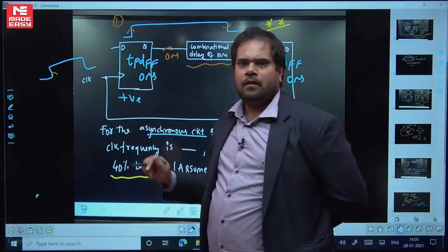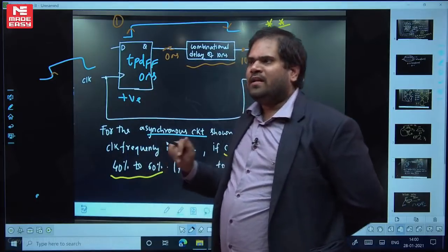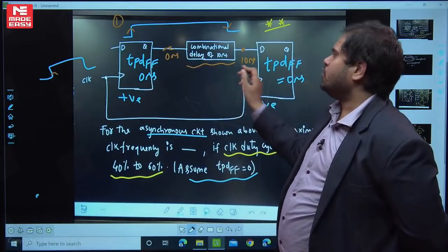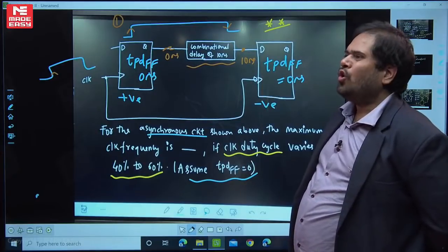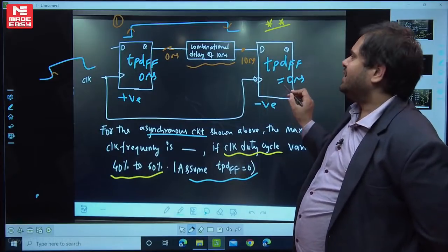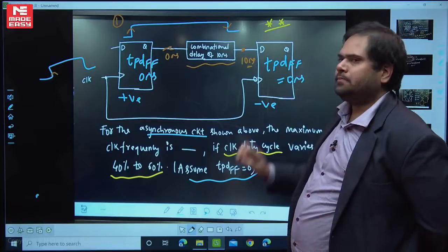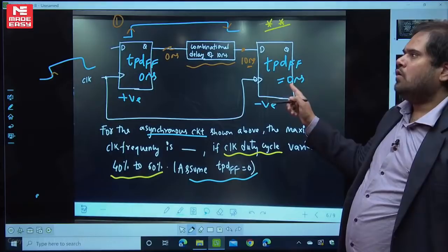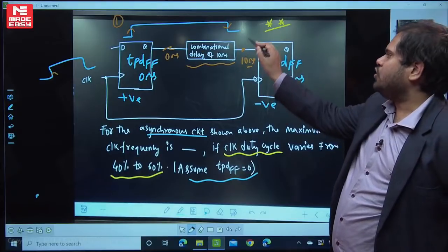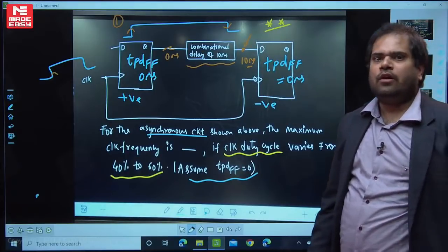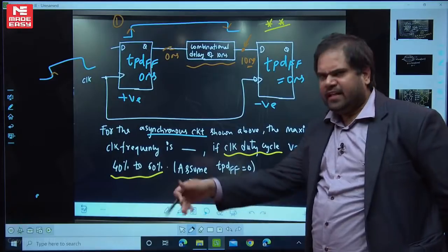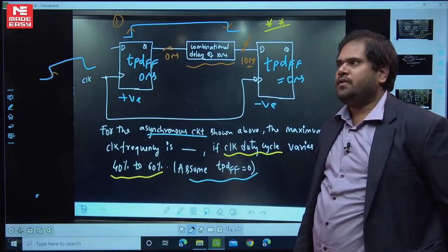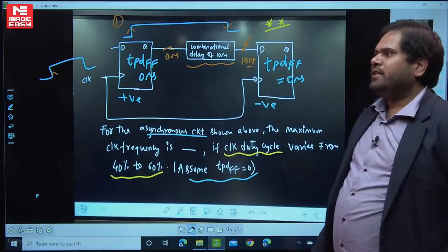पहले ये काम करेगा. First this is going to work. This is coming at 0, but this is going to come at 10. Don't you think this should work only after 10 nanoseconds? This fellow should work only after this because this should become stable, right? We have something called setup time, hold time constraints. We'll see in the next questions. वो बहुत important है for easy.